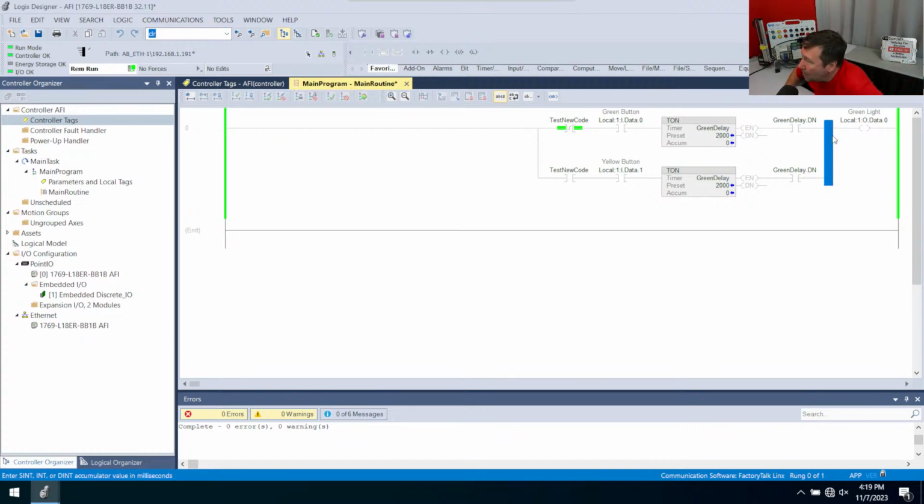At that point, it comes here. And then this instruction looks for a 1. We can mouse over it, see it has a 0. So this is false. And what a lot of you do is you move on since it's false. But no, this went and looked for a 1 and it was false. It still moves on to the next instruction. This goes and looks for a 1 over at the yellow light, and it is false. 2 falses don't make a true.